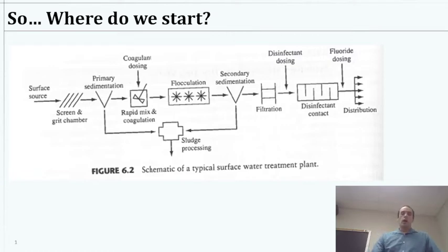So that's where we're going to be today. We definitely use sedimentation for bacteria in a wastewater treatment plant, once we let them grow up to such high numbers that they form little particles and stick together. So we'll definitely see this even in our wastewater treatment segment.